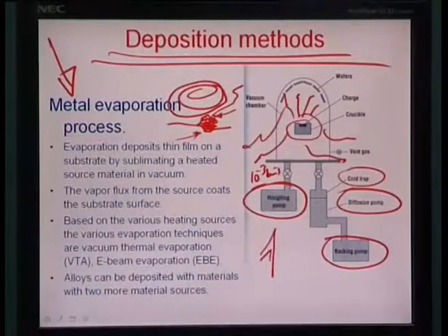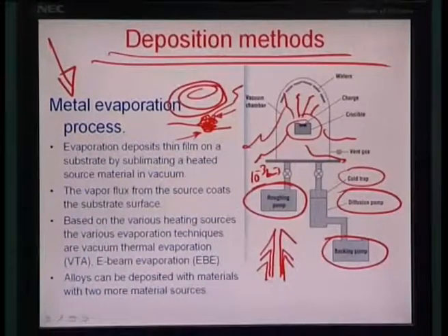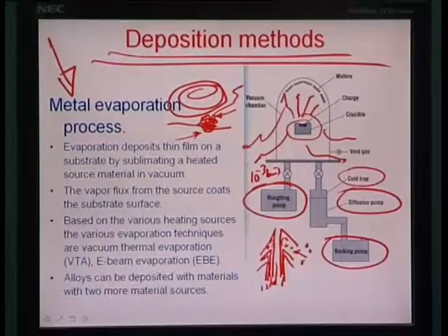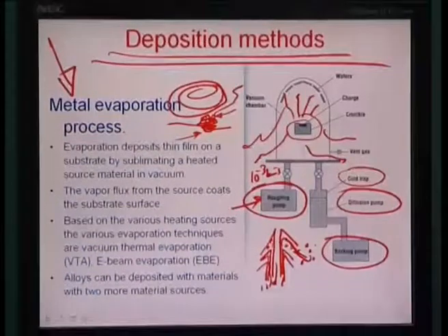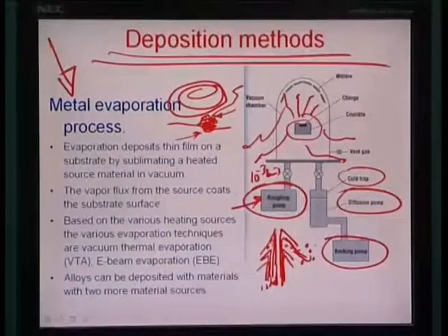You have these fins at different levels on both sides, and you have oil vapors which go into this particular area, and there is a high vacuum pull in this direction. So the oil vapors which are left in this area absorb whatever little bit of molecules are left over in the chamber after the roughing vacuum has been achieved, and take the absorbed molecules along with them back to the roughing pump. That is the way the oil diffusion pump really works.